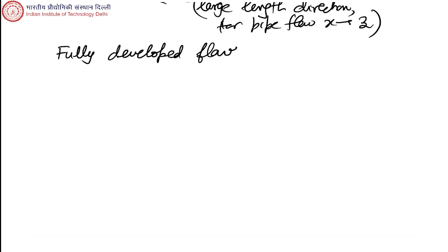And this is what, at least parochially, I call converting English into maths. If I say flow is steady, you have to think partial by partial t is 0. If flow is fully developed, you look at the major velocity in that direction, the flow is not changing, so it means partial v by partial x will be 0, and so on, and then we will solve.